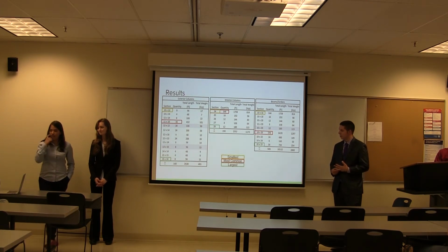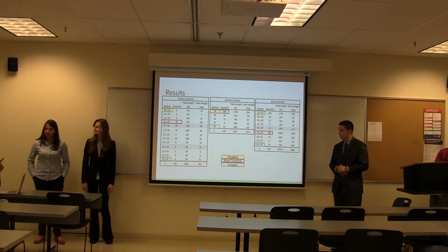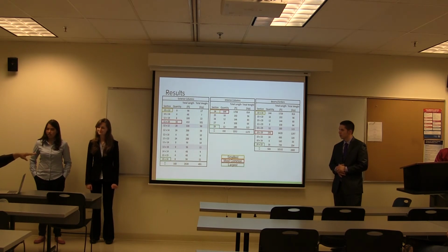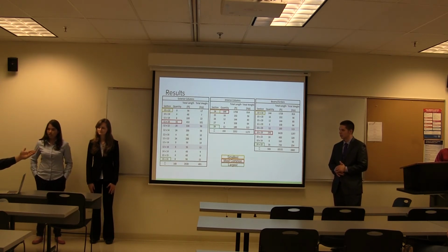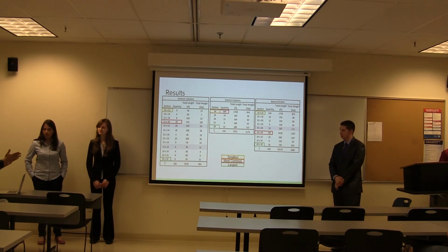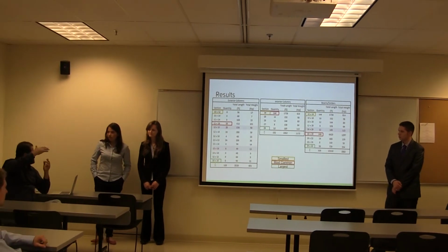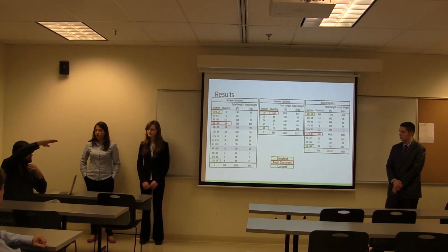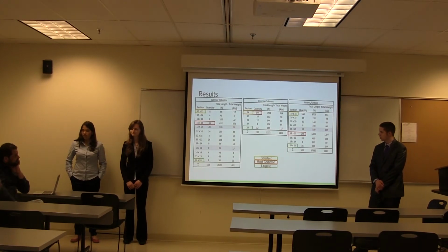A girder section typically, you can justify this. You can answer me by one thing: you can tell me that we don't want to exceed 2 feet, so we don't exceed the clearance limitation. So we had to go with the maximum of 22 or 24. I thought this is the reason. If there is no limitation on the depth, your B is useless. It's not doing anything to the strength. But if you intended to maintain the clearance, not to have a section over 2 feet in depth, then that's how we do it. Okay.